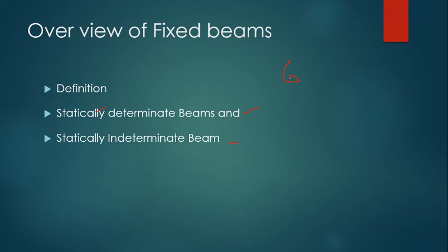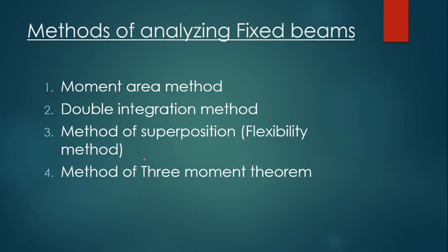So in total we have 6 unknowns, and 6 minus 3 is equal to 3. Therefore, a fixed beam is third degree statically indeterminate. Right. So in fixed beams, for analysis we need to calculate the fixed end moments. Once calculated, it is as good as a simply supported beam with additional couples at both ends. Therefore, the main criterion here lies with the calculation of fixed end moments.